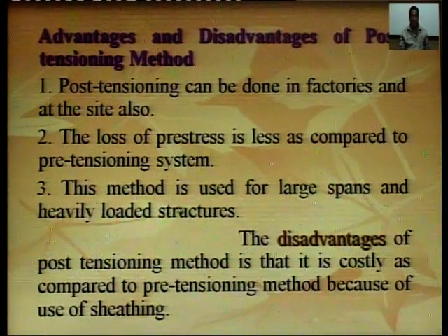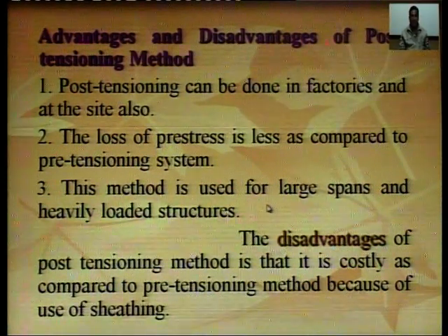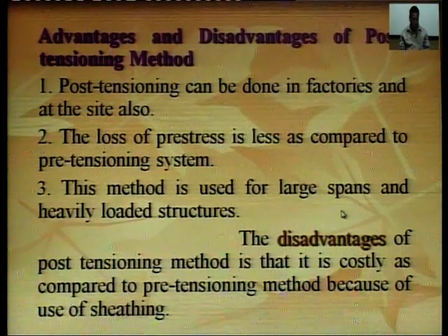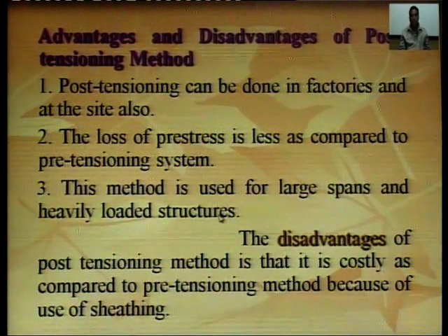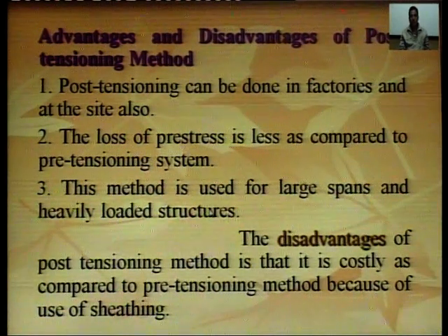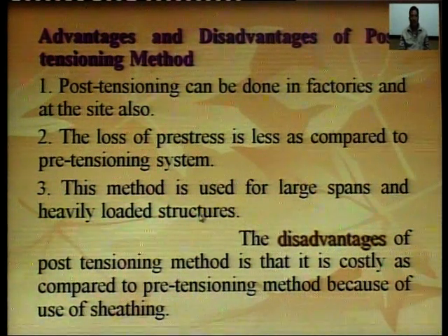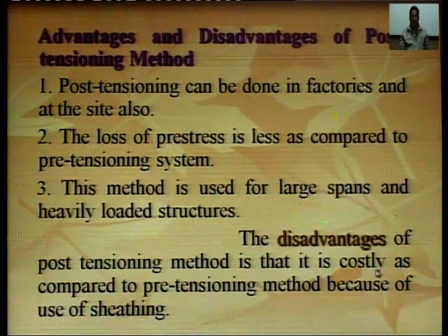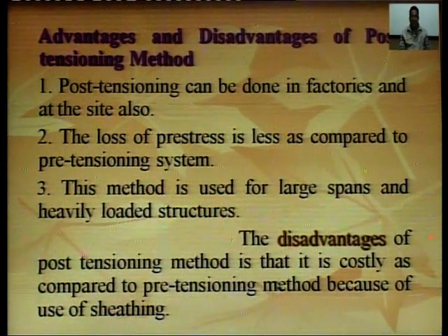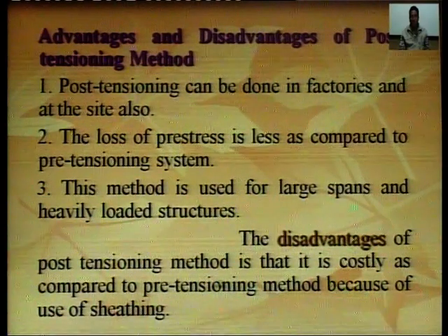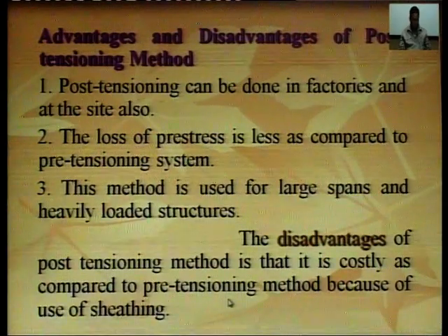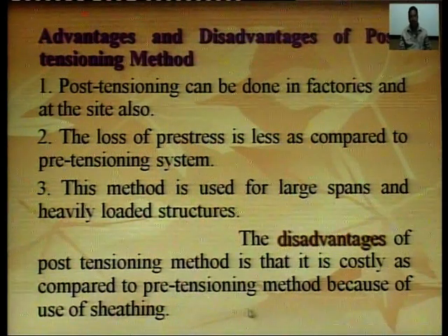This method is used for large span and heavily loaded structures. The disadvantage of the post-tensioning method is that it is costly as compared to the pre-tensioning method because of the use of metal sheathing.